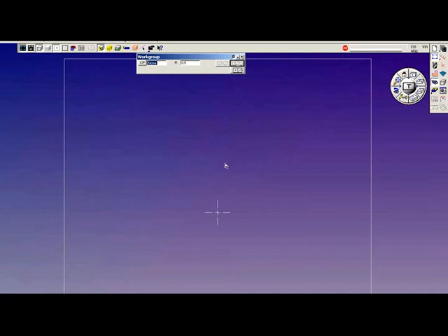In the case of not having a center point, you click on the CP tile and you specify the center point in X, Y, and Z coordinates with the radius value, and you draw your circle like so.